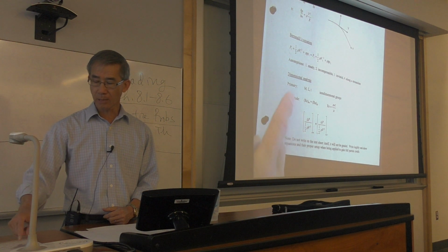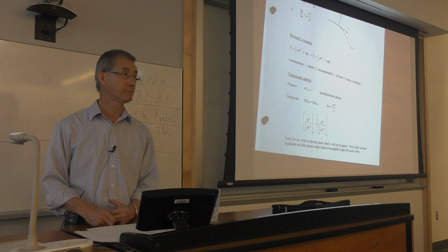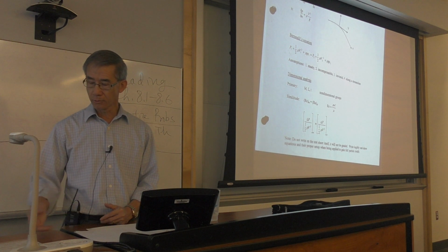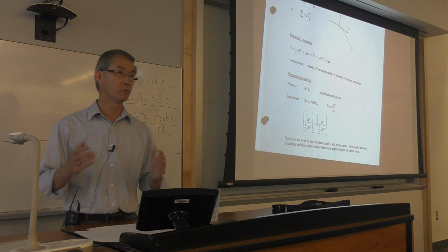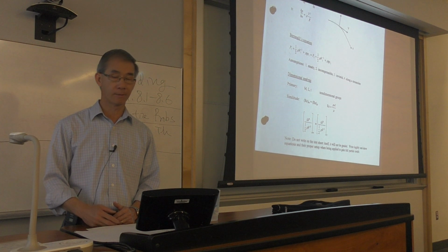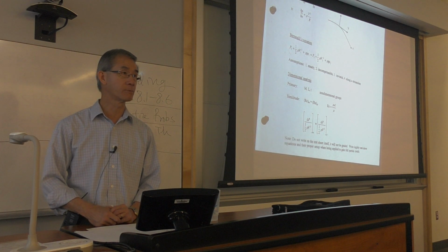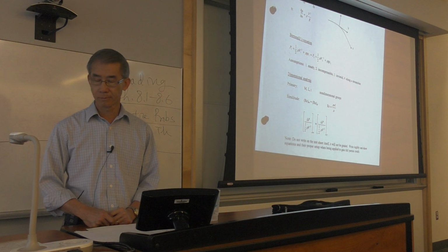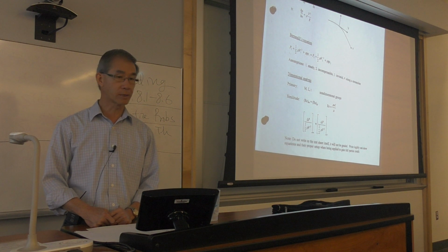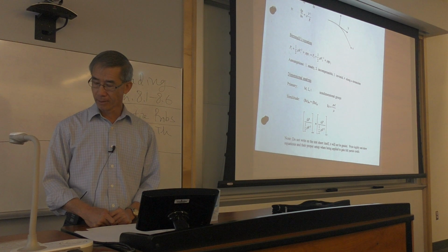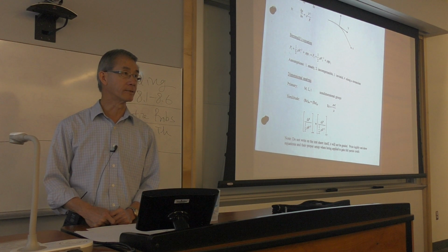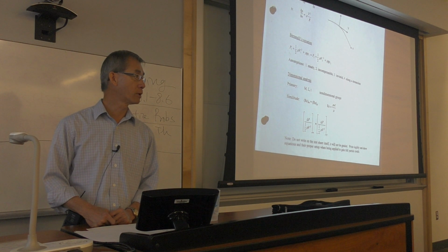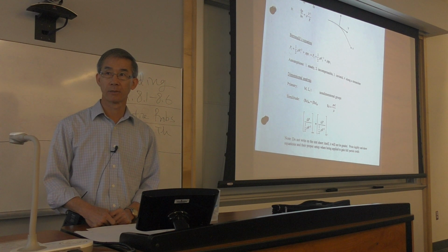So primary dimensions of mass, length, and time, and how you use similitude to do cheap experiments by matching all the dimensionless parameters, Reynolds number, pressure coefficient, drag coefficient, etc. And from that, you can do model testing. Any question on that? Can you do any other problem that you may not have seen before?